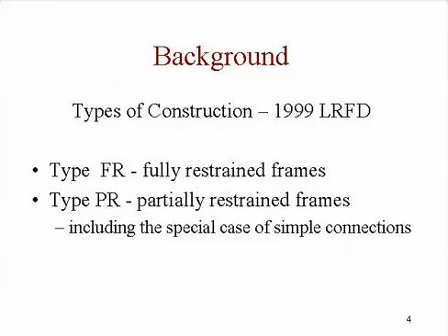PR representing partially restrained. And they said that the simple beam, the simple pin connection, was a special case of the PR connection. Okay? Now, as we talk more about this, it'll be pretty clear that if a simple connection is a special case of PR, so is a rigid connection, just at the other end. But that's what the LRFD spec had.